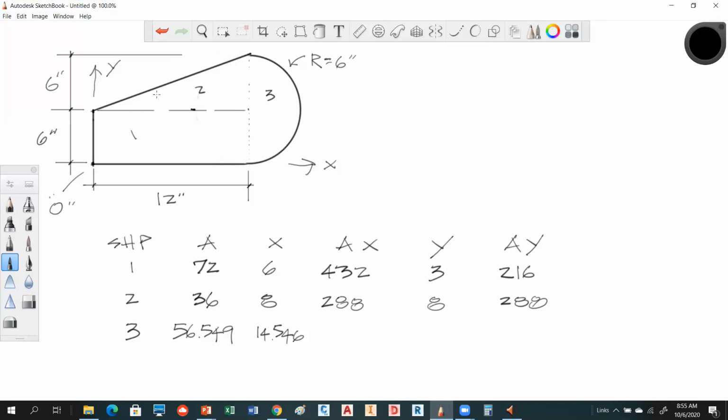So here's what you've got to envision. Maybe this will help. Out here, about right there, there's an axis running through this that would be the balance point of it. You see that? Yeah. And this distance is related by that value, 0.4244R. But we need to come from here to that line, right?